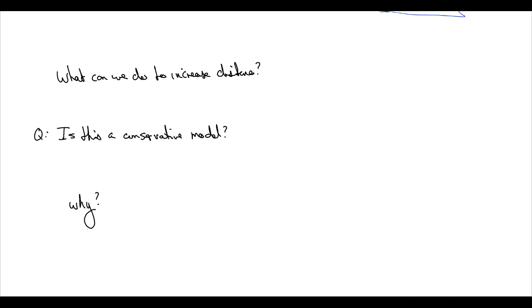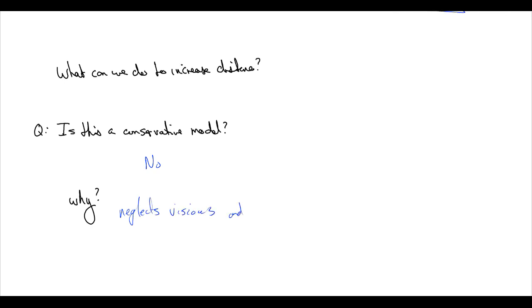All right. So, is this a conservative model? And the answer is no. In fact, the tower will likely fail at a shorter height than what this model predicts. And the reason is this neglects viscous and dynamic forces. The big one here is viscous forces.